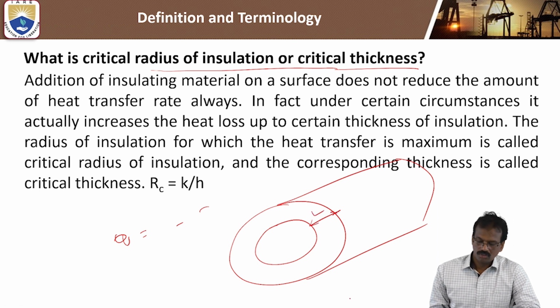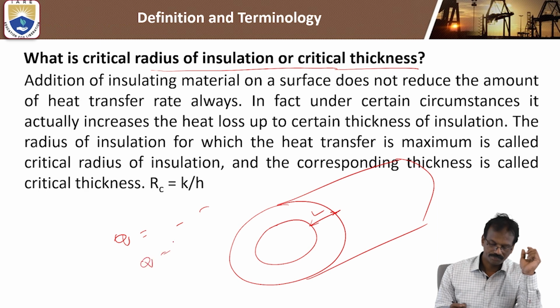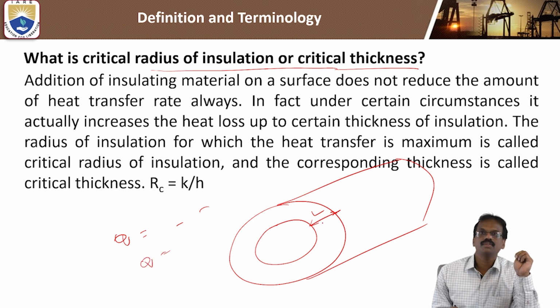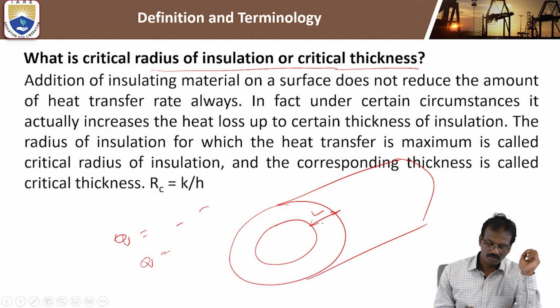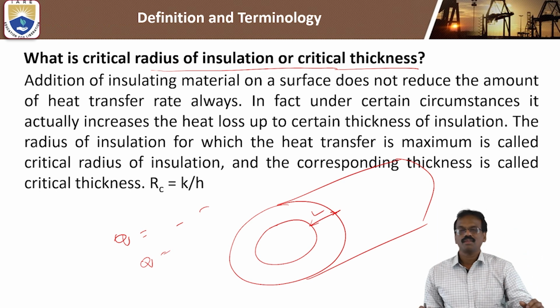If the thickness of the cylinder increases, initially Q will decrease. But then if you keep increasing the thickness of this cylinder, Q will increase instead of decreasing. But in the case of slabs, it will decrease, no problem.